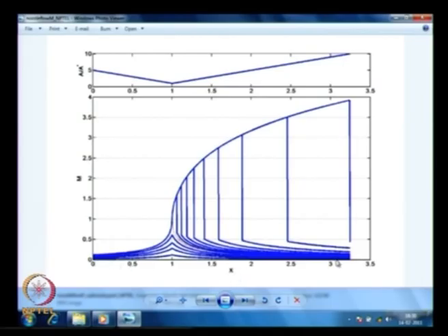For the same set of Pb by P01 I used to plot in the previous case. Okay. If you look at very low Pb by P01 values, very close to 1, all the curves are here, it is going through fully subsonic solution and then it is going back to low subsonic. It increases closer to sonic, goes back down to low subsonic. There is a point where it becomes sonic and then goes through this path, that dotted red line is our P critical 1 pressure P back.